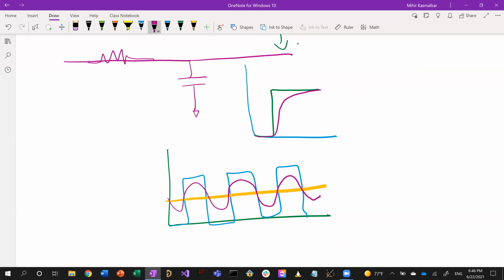Then you add in another sine wave at 3 times that frequency, another one at 5 times, then 7 times, and so on. You add up all these odd harmonics, these odd multiples of the fundamental frequency, and you make that square wave as you keep adding those harmonics.